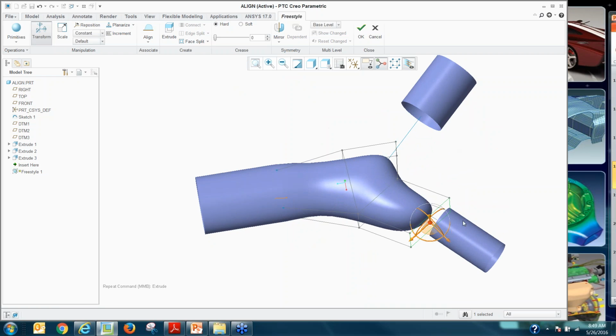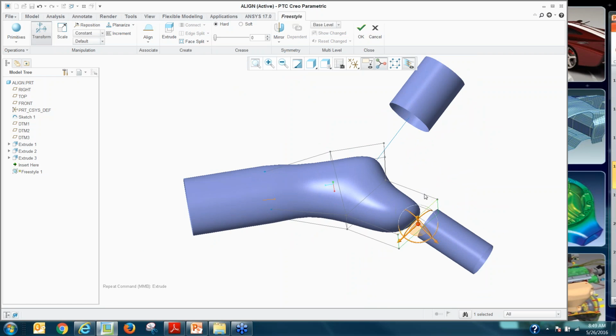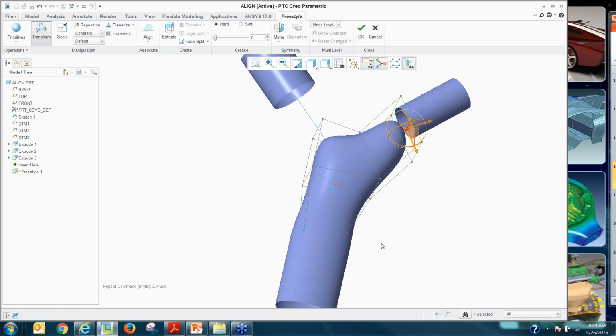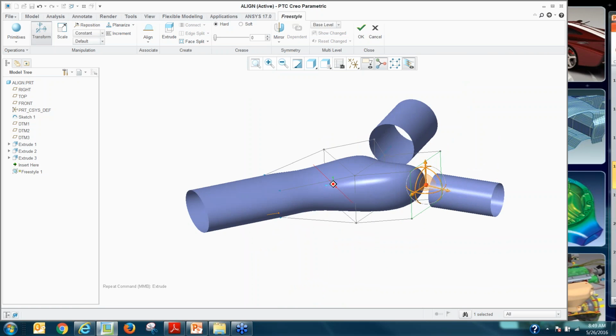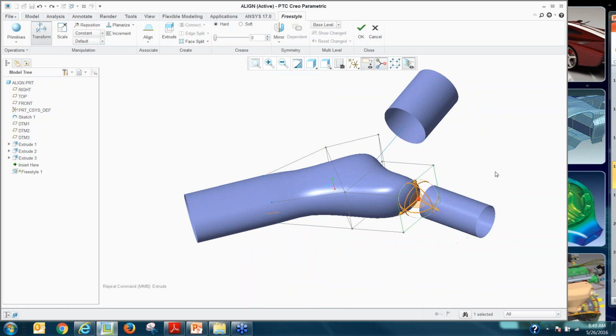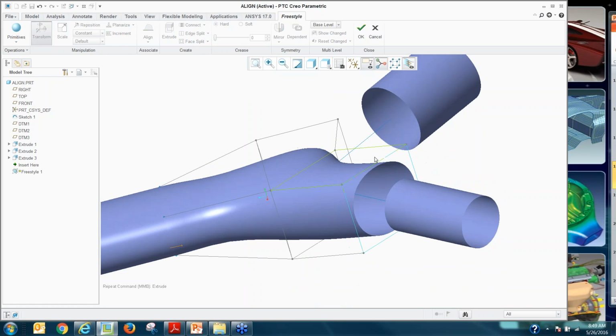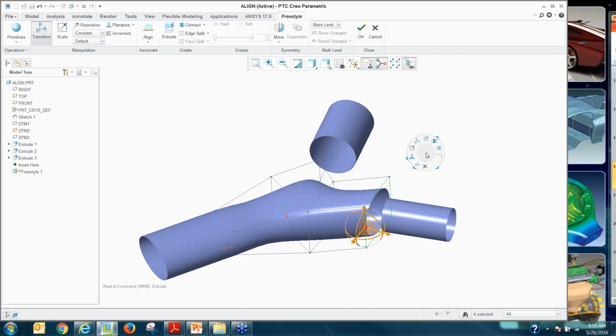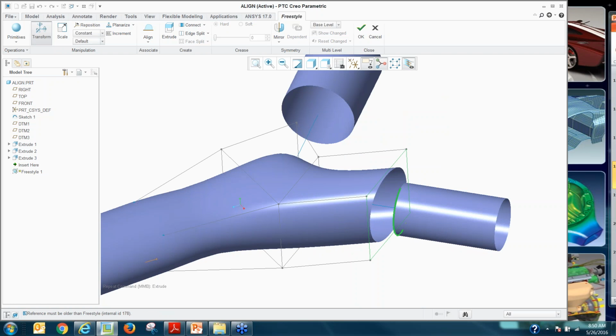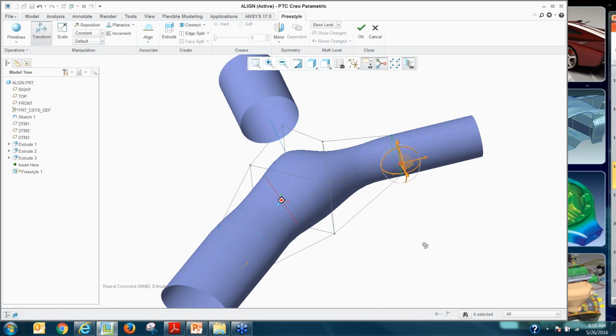So you see how you're still having your parametric control, but this shape here, it's going to take forever for you to connect these using your regular tools. You may be a surfacing guru, but it's still going to take a little bit for you to create those. And this is where I think the benefit of FreeStyle is, to control and to align it. So for example, right here, if I delete that patch, I could do the same thing that I did at the other end. Start selecting those edges of the control mesh. So I'm really using the control mesh here, and I'm saying I want to do a normal alignment on this curve. There it goes.